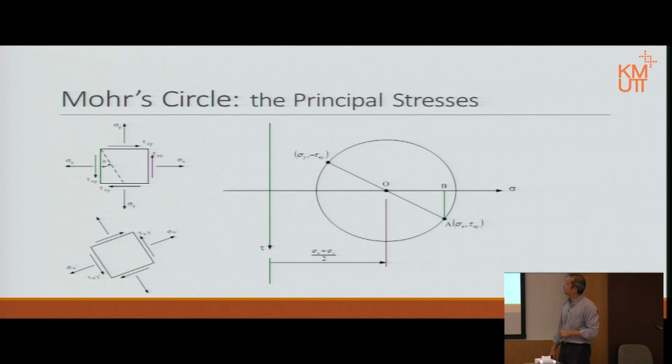Now, let's look at the principal stresses using the circle. So that is sigma 1, 0, and sigma 2, 0. Again, 0 means the shear stress is 0 when it pairs with the maximum and minimum principal stress, the same as our equation proof. And of course, the tangent, notice that it is again the same equation we proved from mathematics.